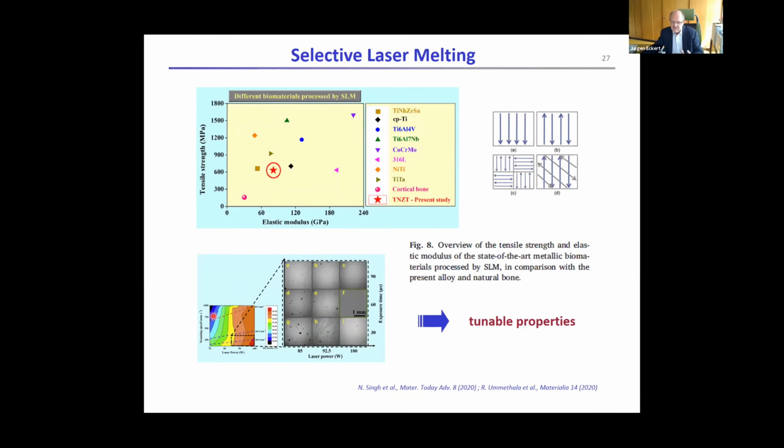And the lower left-hand figures simply show you again that if you do additive manufacturing, it very much depends on the laser power that you couple in and on the scanning speed, because this all affects the phase formation, the porosity, and what kind of anisotropy you may have in your built part, including possible variations of the hatch style, of the scan strategy that you may use. All these schematics simply indicate, okay, the arrows are basically the way the laser runs. You can do this in a variety of different hatch styles. And this gives you a wealth of possibilities to really tune the properties.